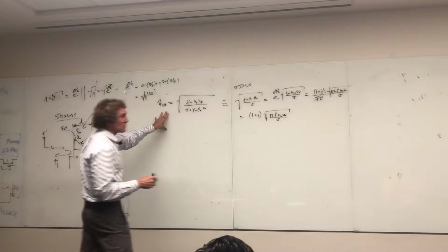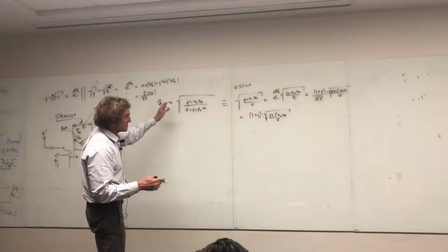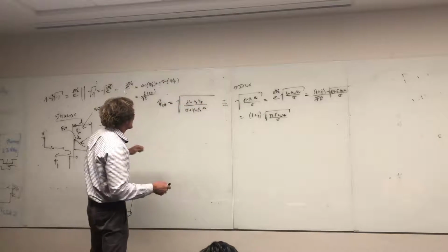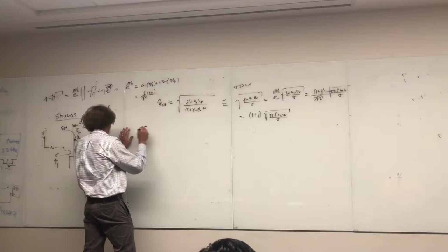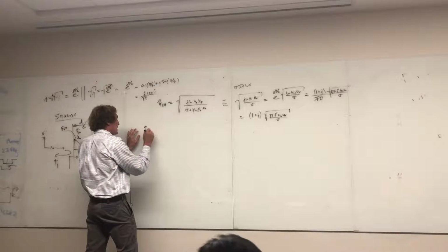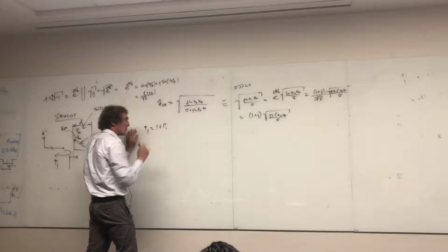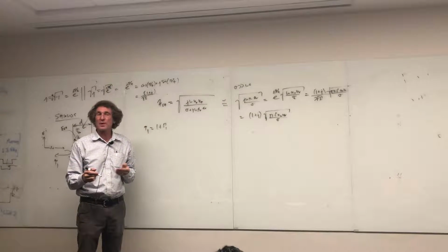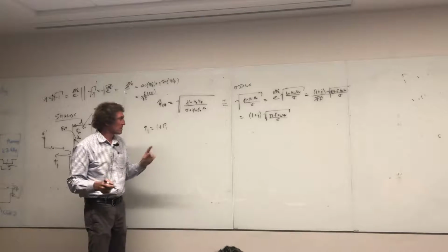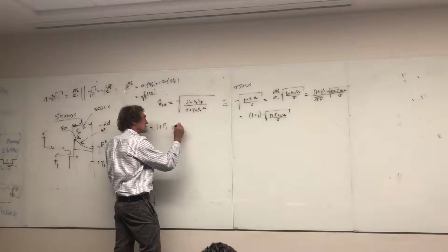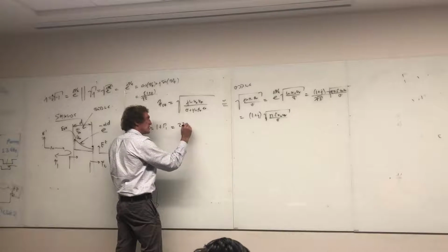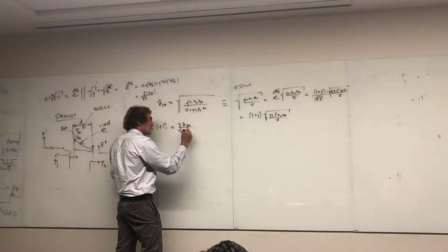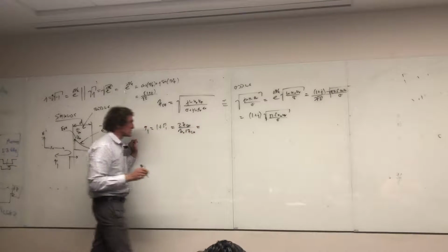You get eta shield first right here. Next, it doesn't matter what form, almost always that's going to be the case. So you're going to get one of these forms for eta shield. Then you get the transmission coefficient of the first layer. Now that's equal to 1 plus the reflection coefficient of the layer between eta naught and eta shield. You add 1 plus reflection, you get transmission. The common way to write this is 2 times eta shield, twice the actual impedance you're going into, divided by eta naught plus eta shield. That's normally the way it's written.